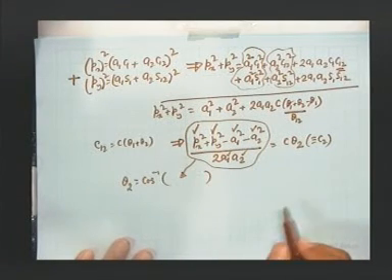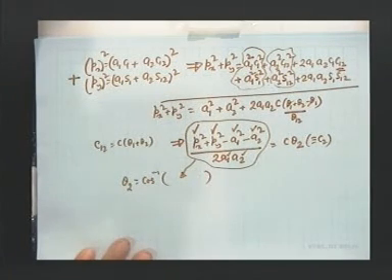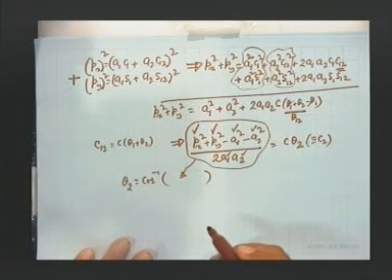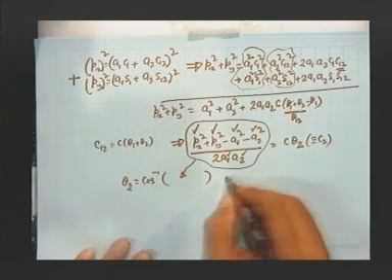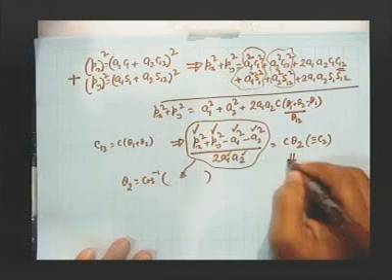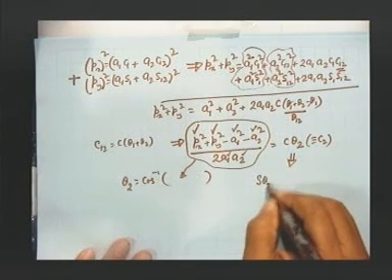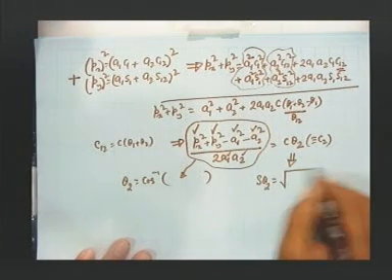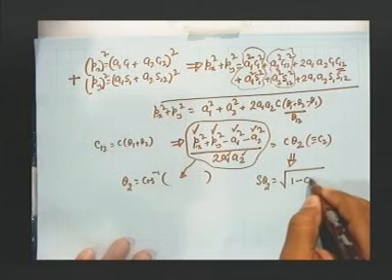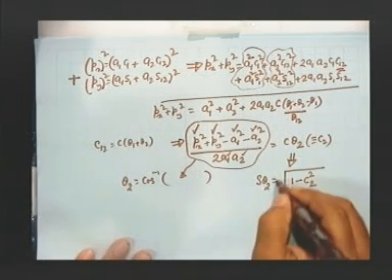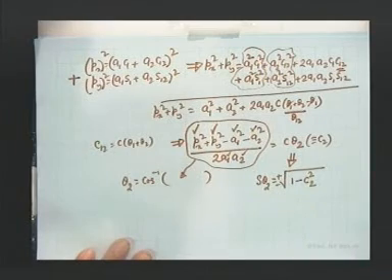But I will not calculate theta 2 using cos inverse. In our mathematical fundamentals class, I told you any angle we should find using atan or atan2 function. So, from here I would rather first find sin theta 2 as square root of 1 minus cos square theta 2, and here I will have plus minus sin.